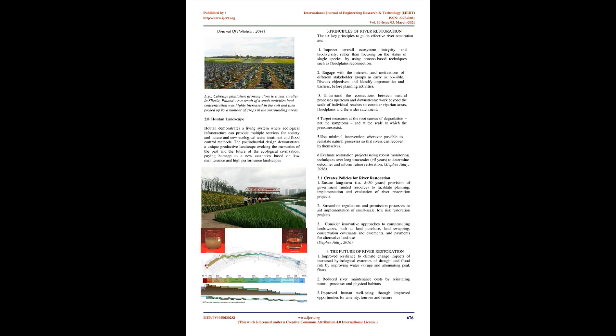Phytoremediation. Phytoremediation is the direct use of living green plants for in situ, or in place, removal, degradation, or containment of contaminants in soils, sludges, sediments, surface water and groundwater. Phytoremediation is a low-cost, solar energy-driven cleanup technique. Most useful at sites with shallow, low levels of contamination. Useful for treating a wide variety of environmental contaminants. Effective with, or in some cases in place of, mechanical cleanup methods.